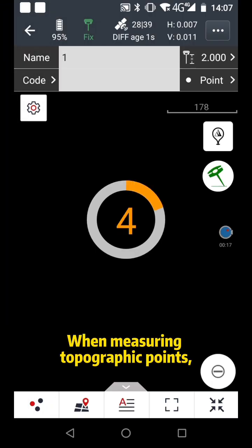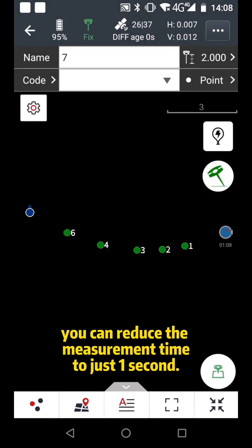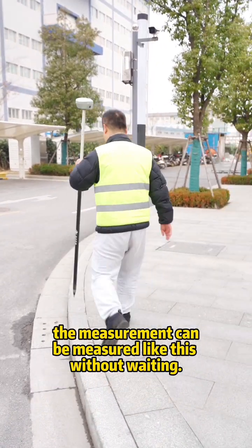When measuring topographic points, the default setting is for 5 seconds. By tapping on quick point, you can reduce the measurement time to just 1 second. The measurement can be measured like this without waiting.